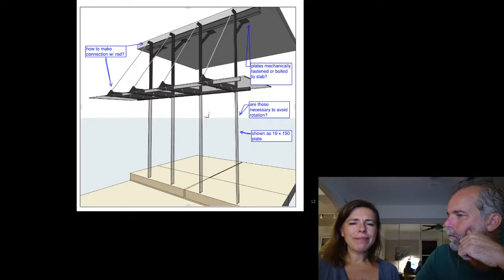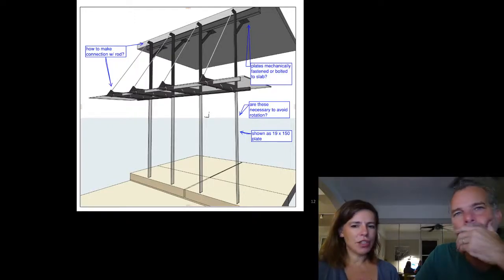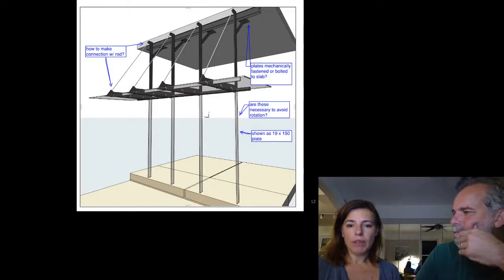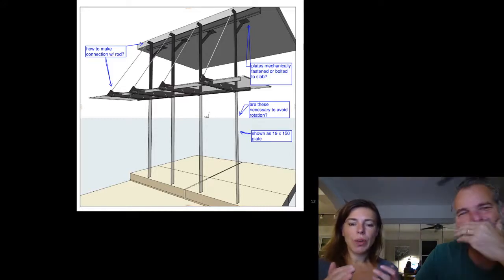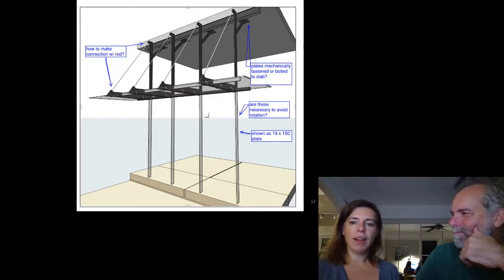I was like, you know what? These members are bigger. I'm going to go back and just check it without the rods at all. And it worked. We didn't need the rods. So we were going to go through a $20,000 expense for something we didn't actually need anymore. So I was able to tell the architect, listen, if you want those visually, that's fine, but they're not structural.